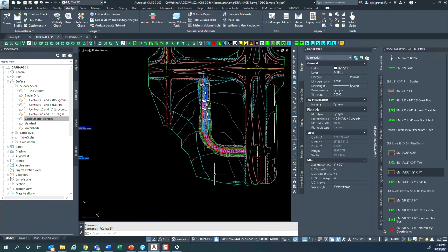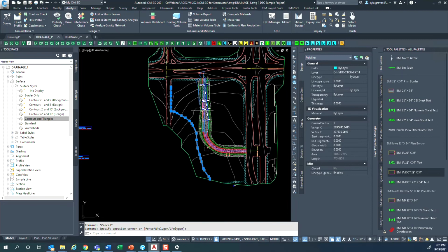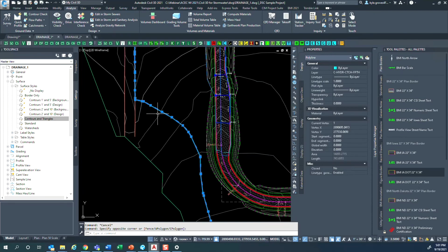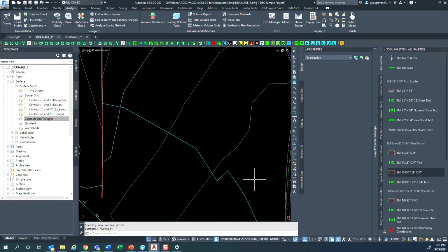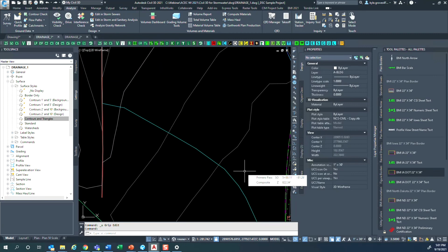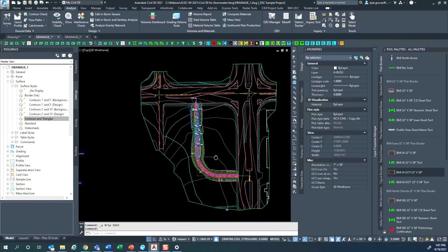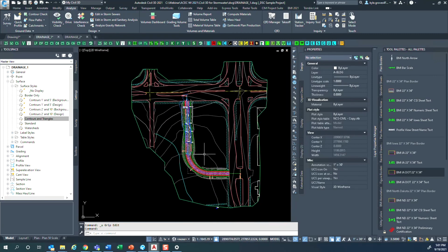However, depending on the data quality of your surface, how tightly you collected your existing conditions, what sort of supplementing factors you used for your proposed conditions, you might want to change some things. Well, no worries, this is a polyline. And yes, I did choose the 2D intentionally because we got that composite surface where we can get our surface data from for our elevations. But this is a polyline. You can come through and you can change where you want these vertices to be. You can add vertices. So this is here to get you started, and you can still manipulate this later on to your heart's content.